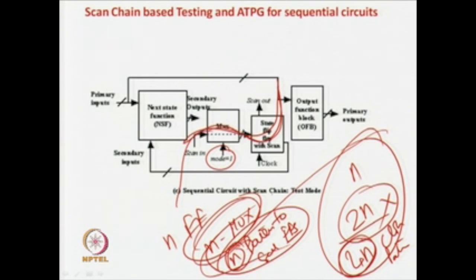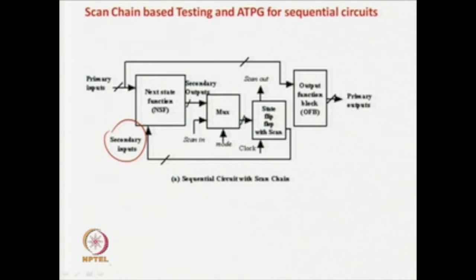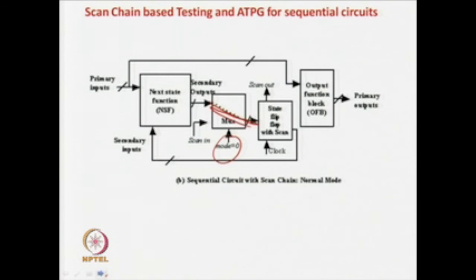And the only thing is that n number of patterns will be required to do this. That is the one problem that still remains and cannot be solved as of now. And one more thing in the case of scan chain: the same clock is there, but now the clock is operating in two different modes, that you have to know. This is a bit complex concept, because when the circuit is operating in the normal mode, the output of these flip flops will go to the combinational cloud, and then again you get the output. So, there is a delay, so your clock has to be a bit slower in this case.